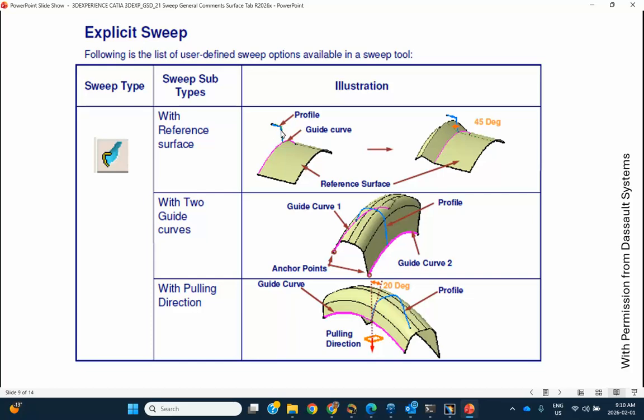You say, for example, I want the vertical axis in that sketch to always line up with the normal to this reference surface. That fixes this plane, preventing it from rigid body rotation about that green direction. That green direction is the direction of the spine, or normal to that plane. Okay?